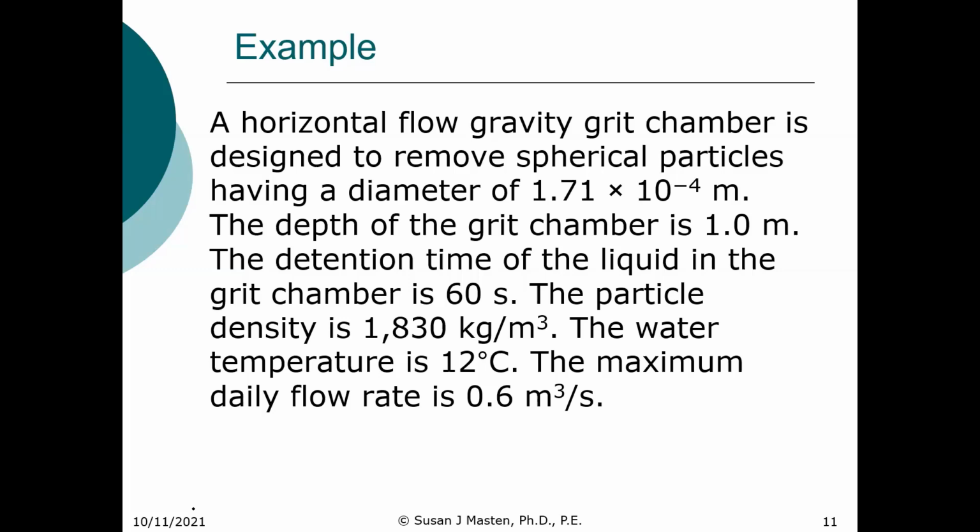The depth of the grit chamber is 1 meter. The detention time of the liquid in the grit chamber is 60 seconds. The particle density is 1,830 kilograms per meter cubed. The water temperature is 12 degrees C, and the maximum daily flow rate is 0.6 cubic meters per second.